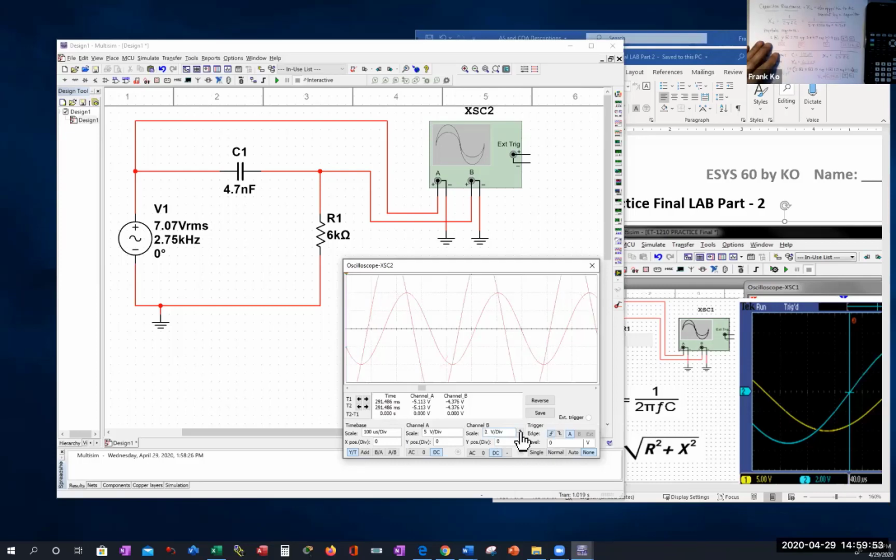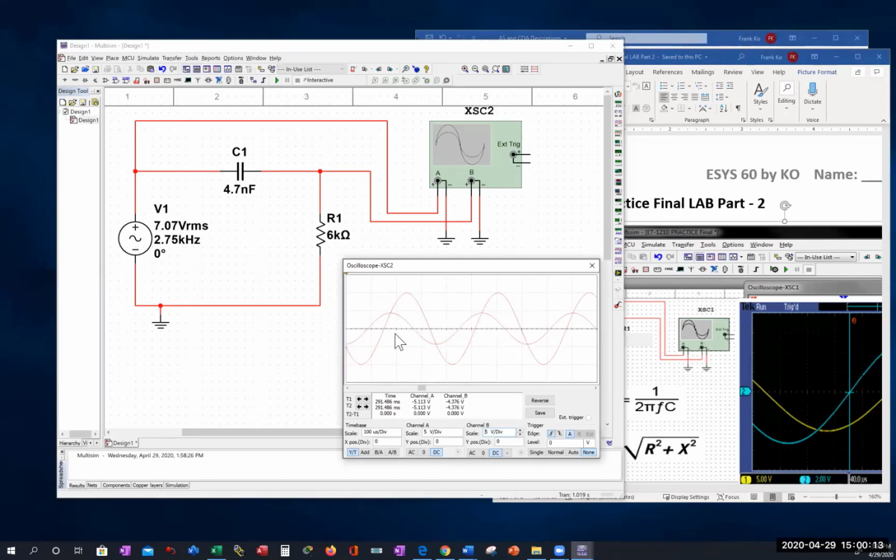So if I bring this down to be the same scale, because that's what we want to compare, both of these at the same scale, if this is at 5 volts per division, this is a little more than 4 volt peak. So we approximated 4.4 volts peak. We're going to check all this out with mathematics in a very short period of time.